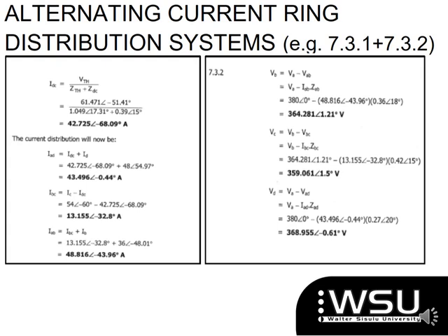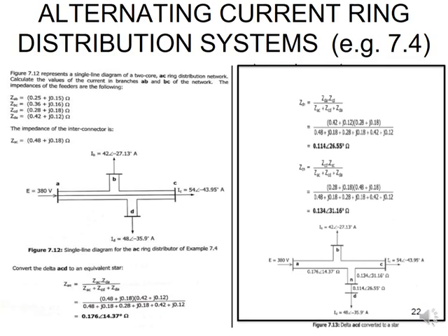So you must just know the different steps. It's a very long way to get to it. Then we go to our second example, which is EG 7.4 in your book. Here they give us the different impedances: ZAB, ZBC, ZCD, and ZDA. You can see that it's a resistance and inductance. They say it's also a two-core system. Remember, I don't need to multiply by the 2 at all. This network also has an interconnector. As you can see, there is a line drawn between your A point and your C point.